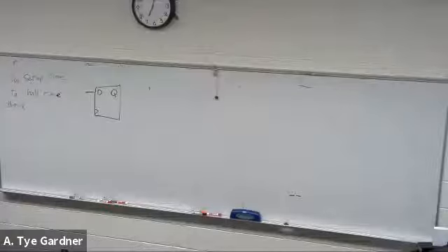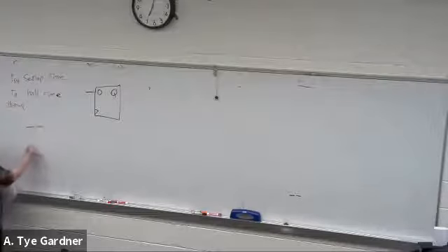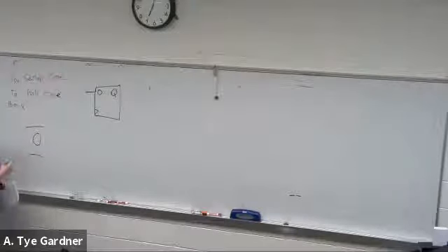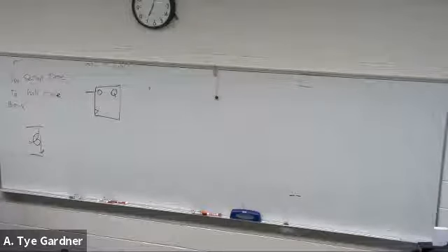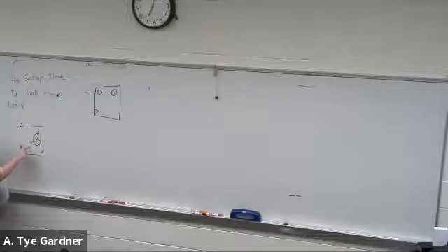Now, the reason for this is device physics. It's really like charging up an input, and it takes some time to do that, and you need to make sure it's had time, and if you don't, instead of being at 1 or 0, it's somewhere in here, and it will latch to one or the other, but you don't really know where, right? So if this is a 1, that's a 0, and I don't meet timing, I don't know where it's going.